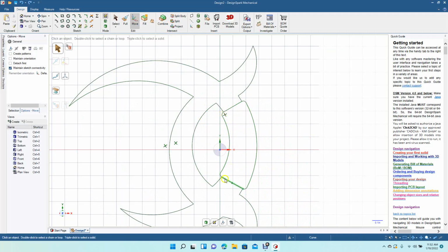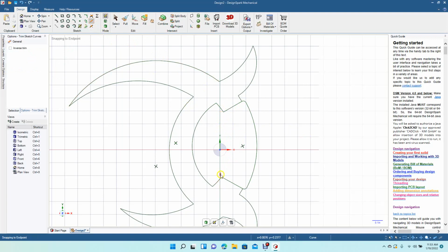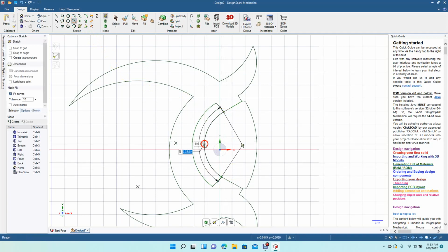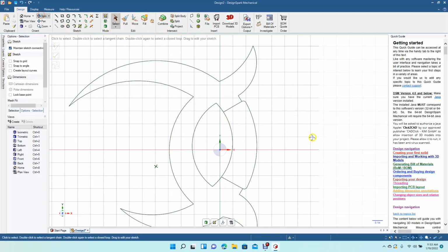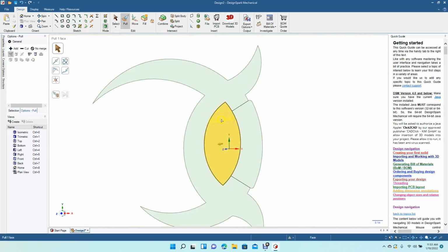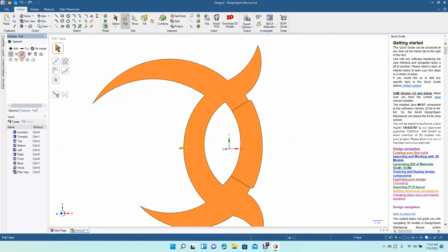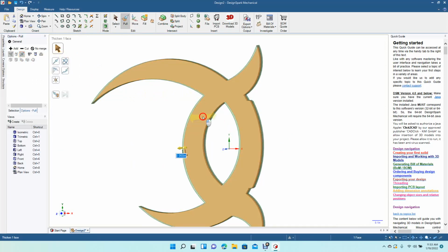So what we're going to have to do is trim. Trim those pieces off right there, and we'll have to add another 3-point arch in there. That has to be closed before we can extrude it. Okay, we'll go 0.550 inches at 69.5 degree angle. Let's go ahead and spin this. Let's give this a pull. Okay, let's delete that. We don't need it. Click that. We'll come over here to pull from both sides. And we'll pull this out.